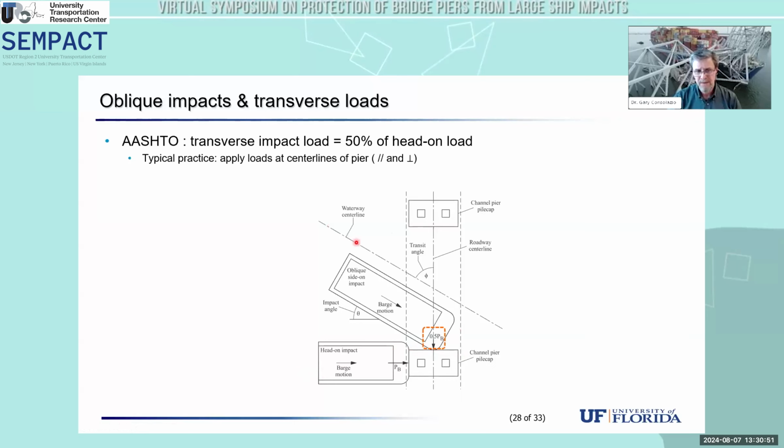If the direction of vessel motion was along this waterway center line, then that head-on impact load would be applied parallel to that, and this 50% load would be applied perpendicular to that waterway center line.